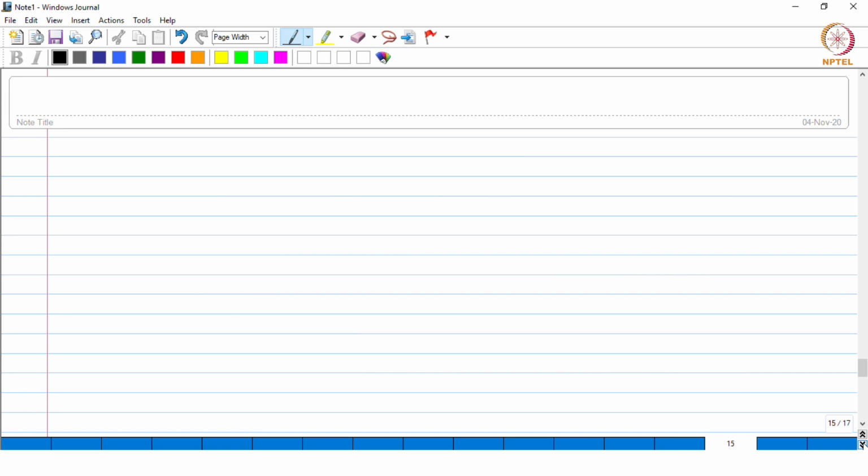Now, it has also been suggested that there is a critical velocity of the solidification front which decides the engulfment to pushing transition. So, this critical velocity is a function of the particle size and the temperature gradient.